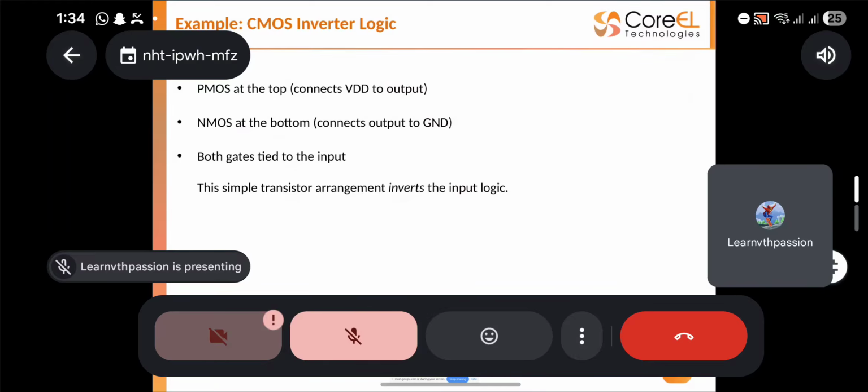You can generate a netlist. Inside that, you can write the truth table. For digital design, for simulation purposes, you will write the test bench instead of forcing the values manually. If you don't want to write a test bench, you can even force the values inside the simulator also. But you can see one output at a time. Similarly, here also we can form the test bench, or else we can directly simulate. That I will show you while performing the demo.